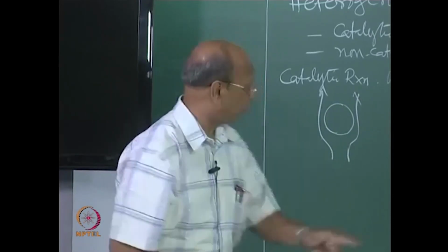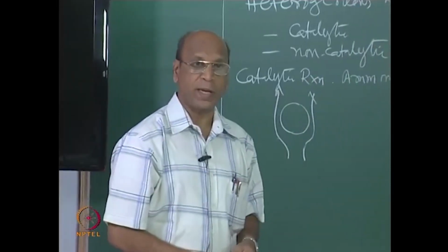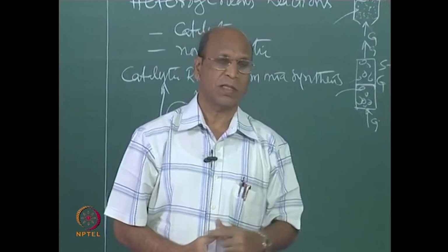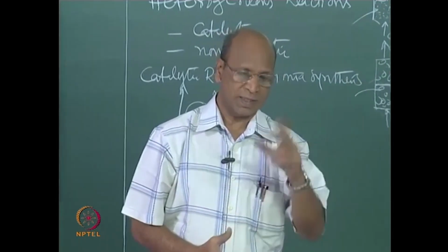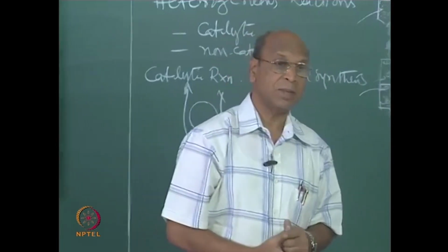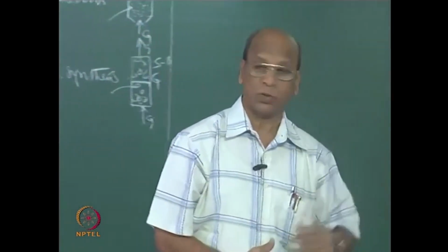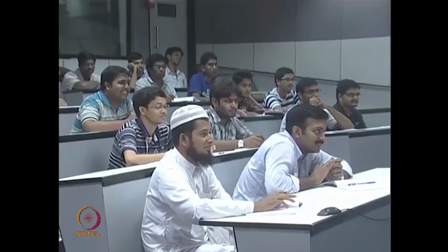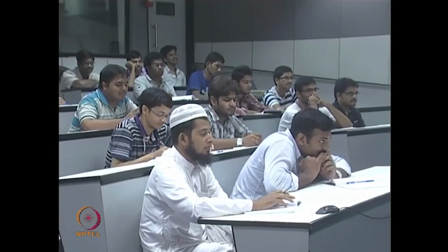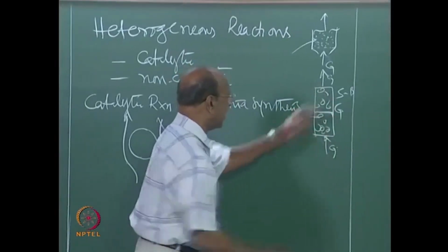That's why please remember, when you are operating a packed bed, it should be in the turbulent Reynolds numbers. What is the Reynolds number for turbulence in a packed bed? Greater than 500. Don't say 40,000 and all that. 40,000 also will be, but I think it starts from 500 onwards. Okay, good, excellent. You remember that. So that is why here you have plug flow, PF.